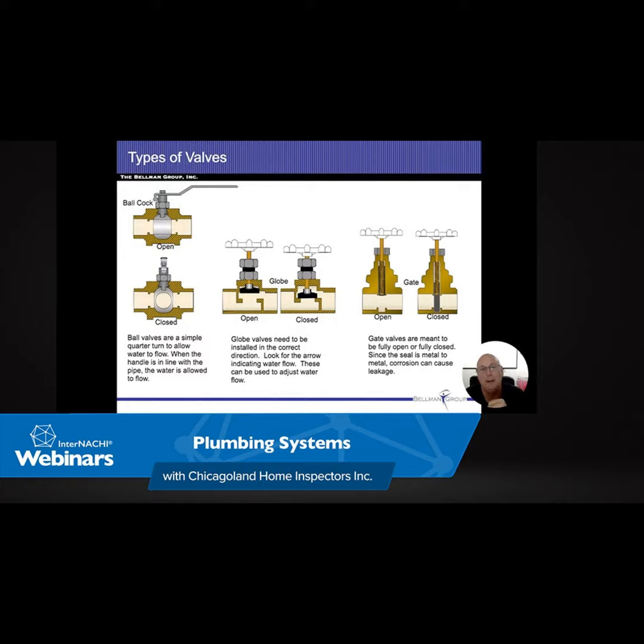But with the different pieces going in the right order and the washer going in the right direction, if you got one of these things backwards or put in wrong, then that fitting is going to leak. The good news is it's going to leak right away, and then you're just going to end up messing with it and putting it in right until you can get it to stop leaking. But I would do a little bit of research on polybutylene and class action lawsuits with it. I think you're going to end up finding it somewhat interesting.